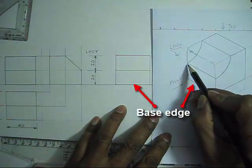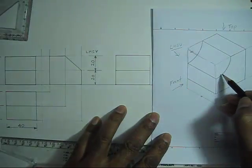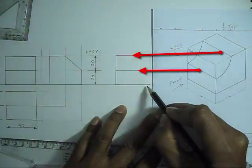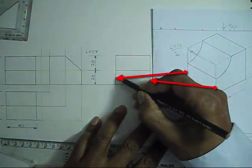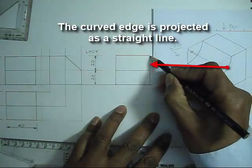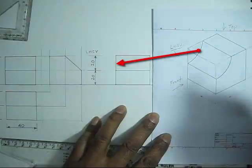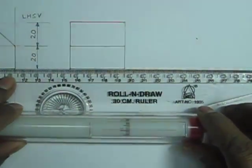The base is represented, the top part is also represented, and the curvature part is represented as a rectangle. So this is the new edge. The top edge is also a new edge because of cutting. On both sides, the curved part is projected as a straight line. So the front view is complete.